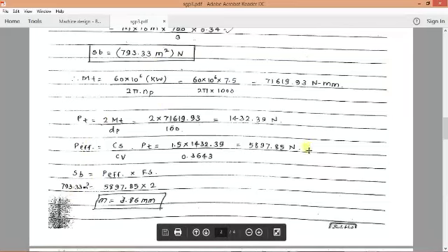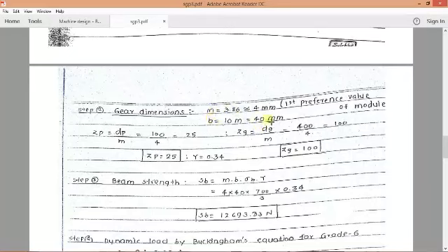So as we mentioned, width is always equal to 10 by m. So b by m is equal to 10. So equating that equation, we get the width of the gear is equal to 40 mm. So again we have to calculate the number of teeth on the pinion and the gear. There is a formula: module is equal to diameter of any gear divided by number of teeth on the gear.